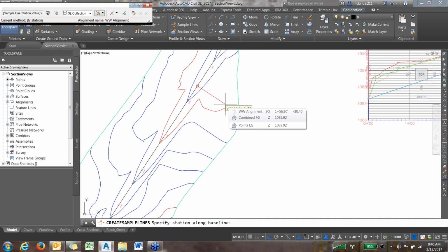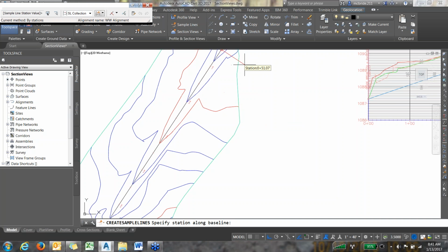However, most districts find out that it is simpler if you just go ahead and put the cross sections on the plans. That way you have something to write on after you do your final construction check. So using that knowledge, I'll go ahead and just do one every 300 feet here, just for simplicity, and I'm going to start at station 100, because if I were to start at station 0, you can see my cross section wouldn't look too good. Okay, it just doesn't have enough information there. So I want to start where I get a good cross section.